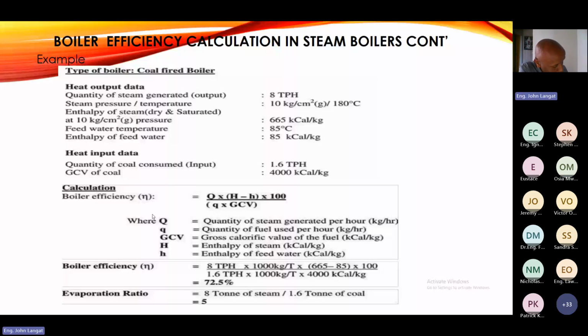Thank you so much. On the issue of boiler blowdown, why boiler blowdown? The reason why you do boiler blowdown is to reduce the amount of total dissolved solids in the boiler water. And what causes total dissolved solids? As I mentioned, most establishments do not treat the feed water to the boiler. And what I mean by not treated is they are not filtered, they are not conditioned properly before being utilized.